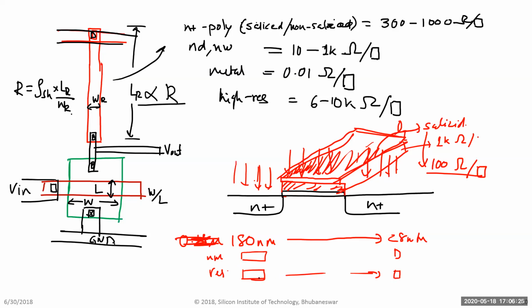Yes, sir. So the short answer is no, in the sense that the scaling in a typical technology is purely done from the MOS perspective. The resistor just so happens to be whatever the gate is. For example, the gate width can be allowed to be as small as 0.18, but in a resistor they will not allow that small a range.